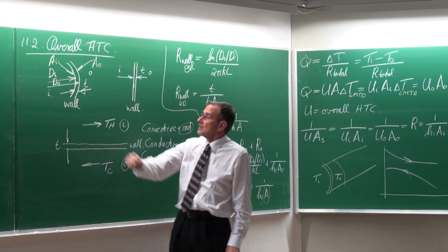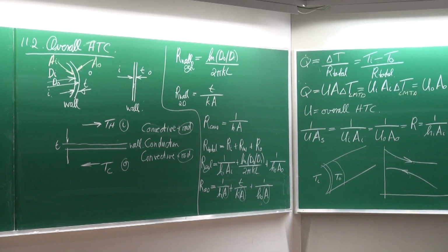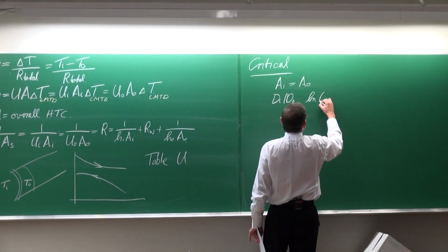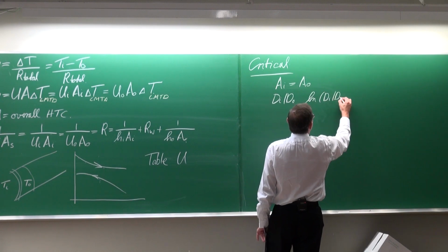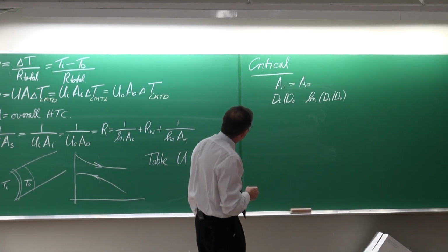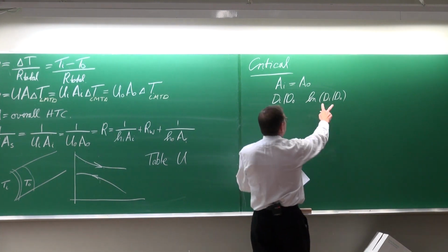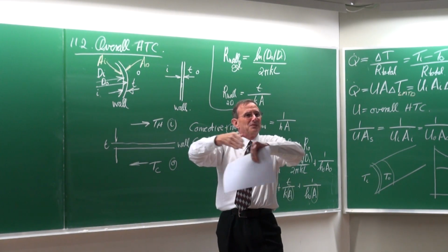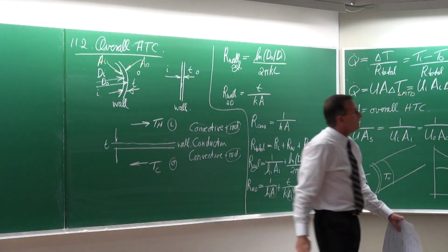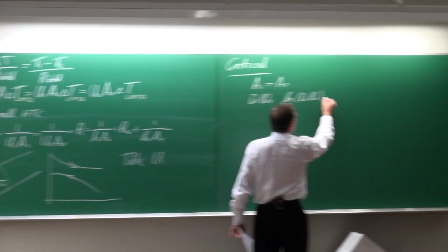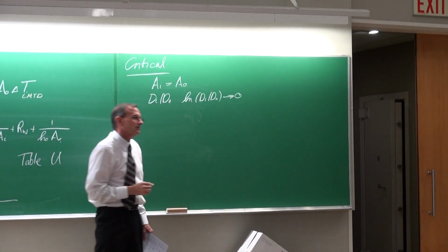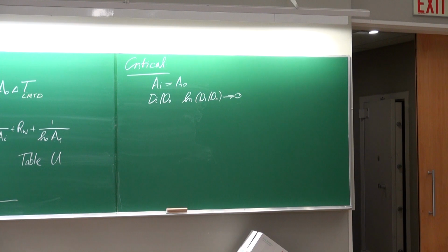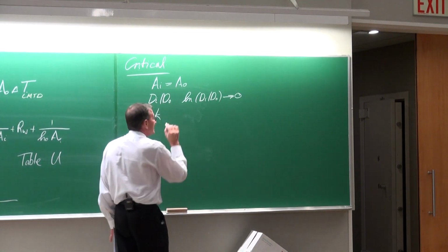Okay, why? Because we've got a ln term there of the ln of the diameter on the inside divided by the outside. If your heat exchanger wall is very thin and the radius quite large, then this is most probably going to go to 0. Okay. So it means that this term is going to disappear. The other thing that you need to check is the thermal conductivity K.